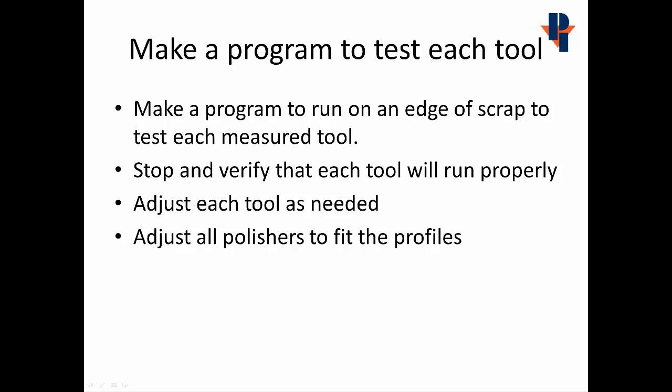After tools are successfully measured, make a program to run on the edge of a scrap to test each of the measured tools. Stop and verify that each tool will run properly. Adjust each tool as needed, and adjust all polishers to fit the profiles.